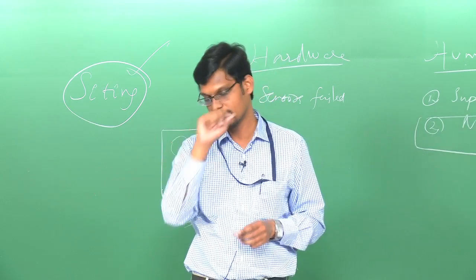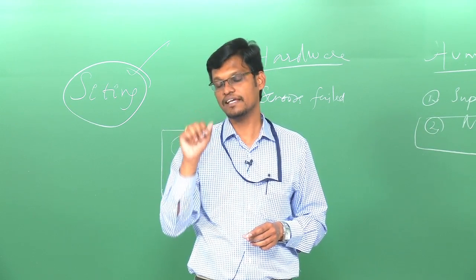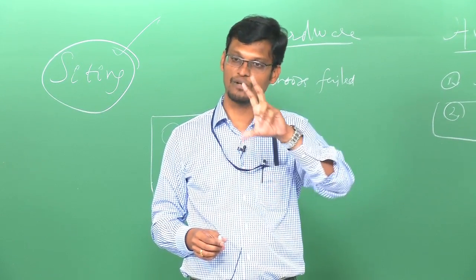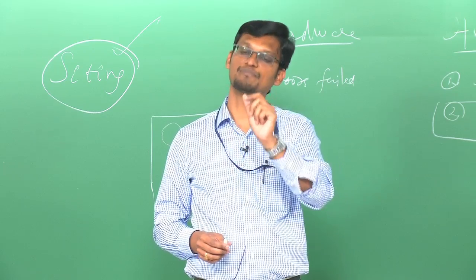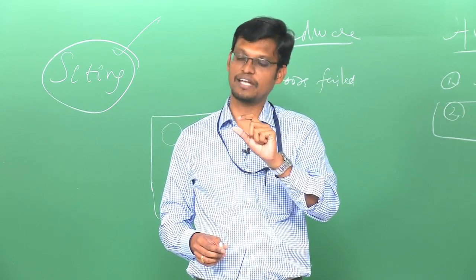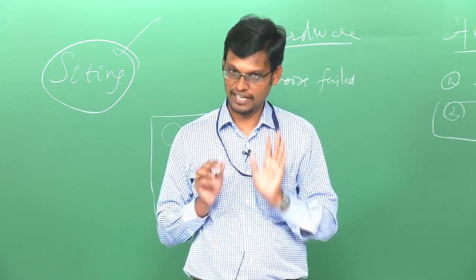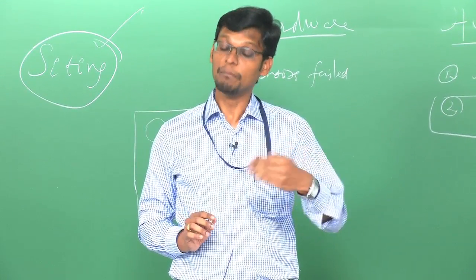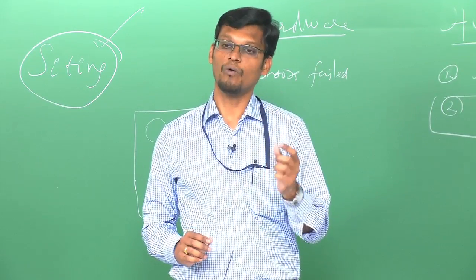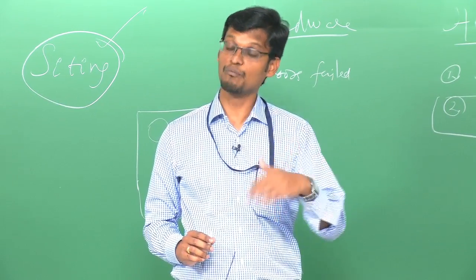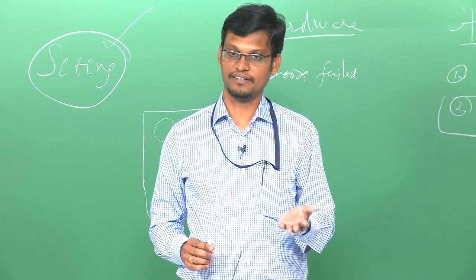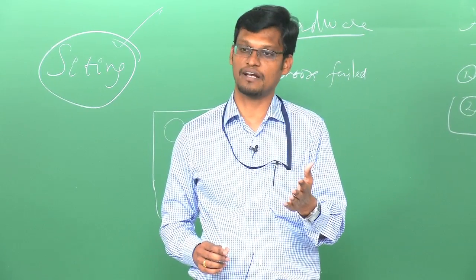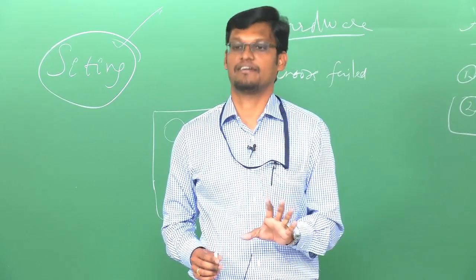The reason being that, historically, the human body in a particular 8-hour shift can only respond within the specified time to so many alarms. For example, in an 8-hour shift, my body is designed to respond immediately if I get 1 alarm in 8 minutes. If I get more alarms than that, then the response time, or the way I logically analyze the response to a particular alarm, will get affected.